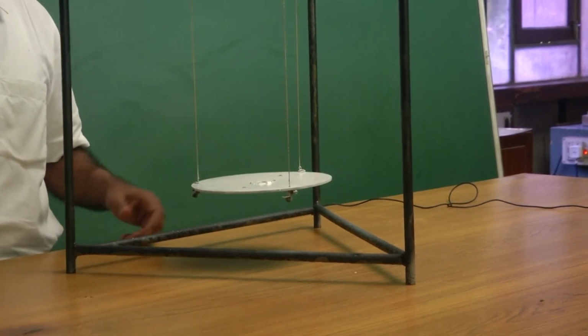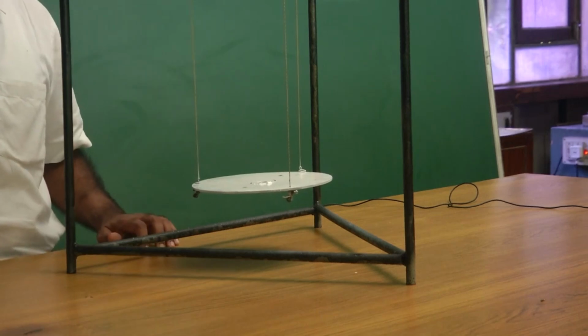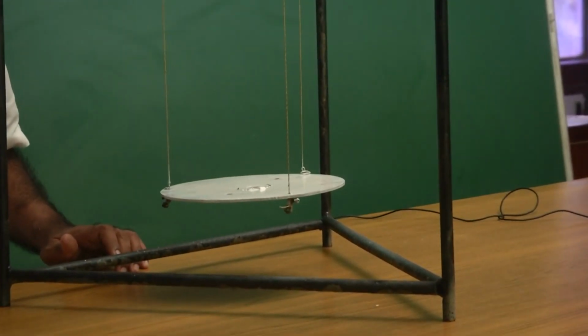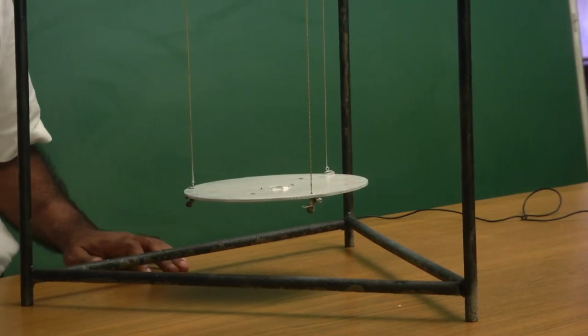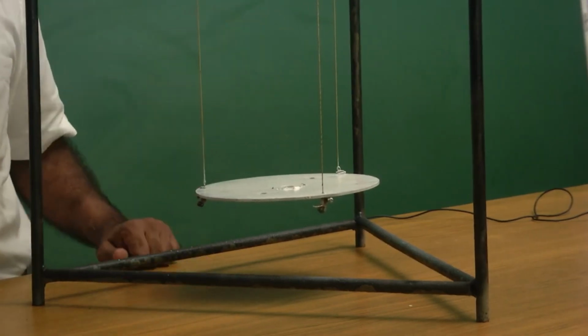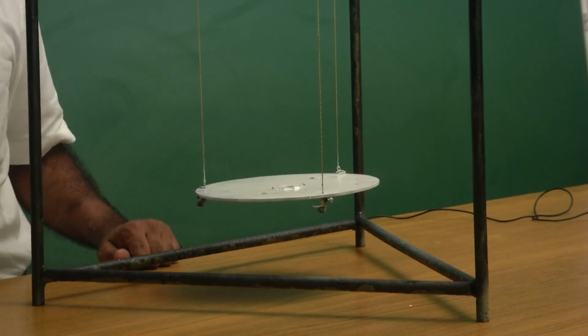So, without the connecting rod and with the connecting rod, that gives me two values of mass moments of inertia, and by subtracting the two I will get the mass moment of inertia of the object that I placed. So, that is how we find the mass moment of inertia of any body about a particular axis, which is not a standard form and shape, as you can notice here.